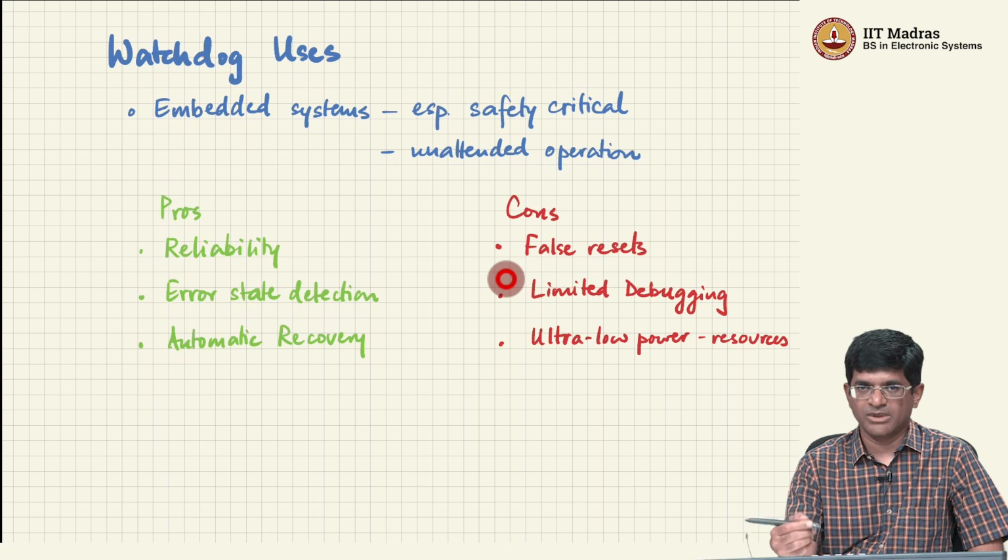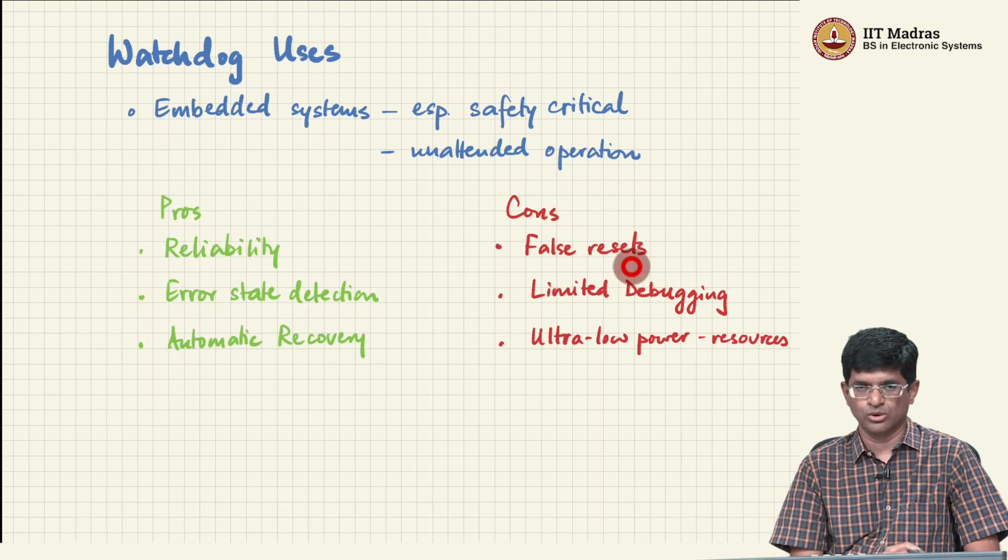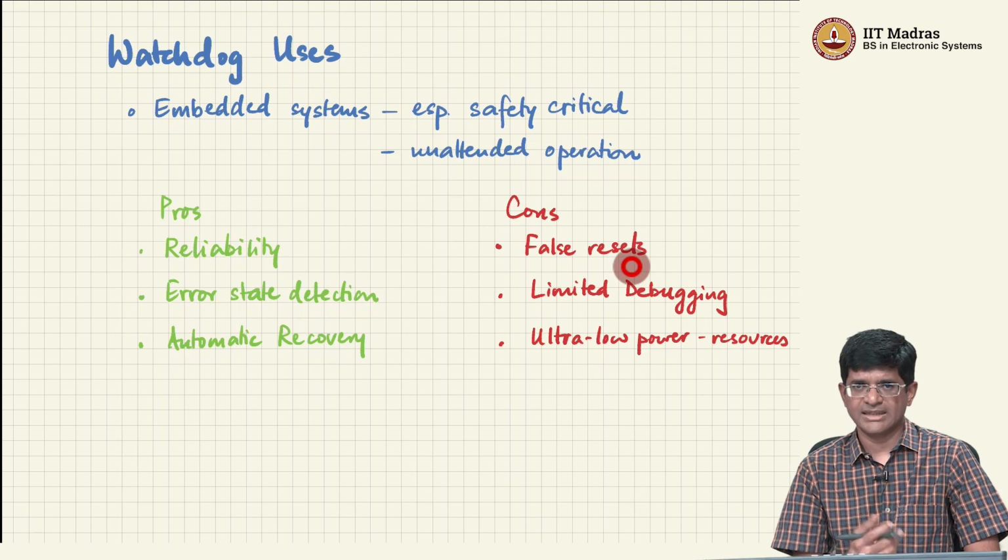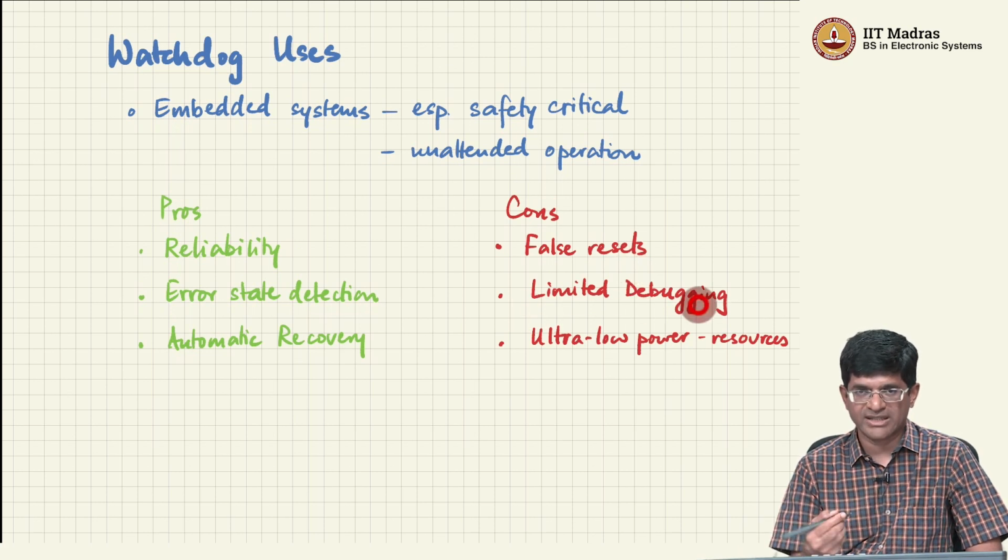The biggest problem that you need to be aware of and careful about is, are you going to end up getting false resets, right? Just because you put your timeout too low, it didn't give it enough time to actually finish the work and just ended up resetting even though the CPU was actually busy doing some computation. Then that becomes a problem. It also gives you limited debugging visibility because it just restarts the system. It doesn't necessarily tell you what went wrong, right?